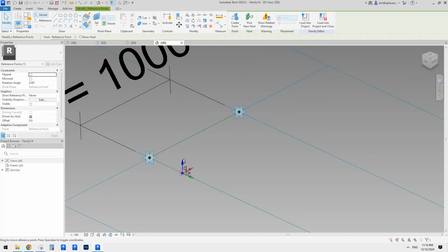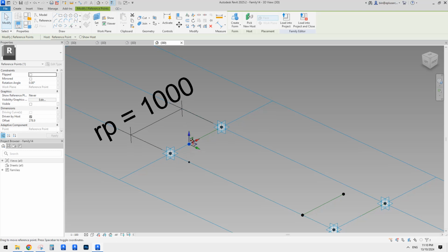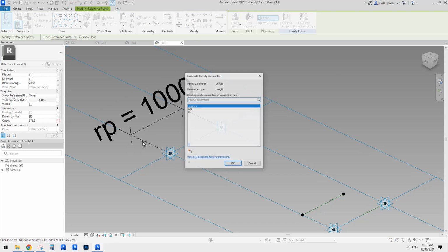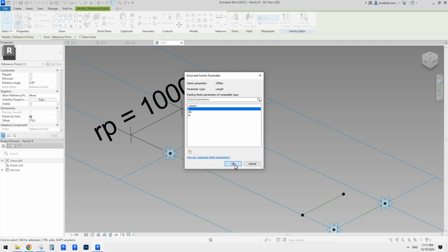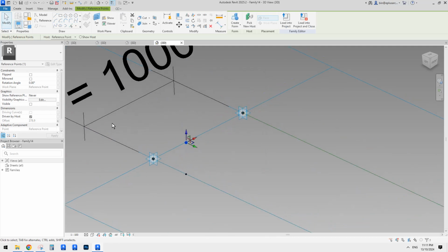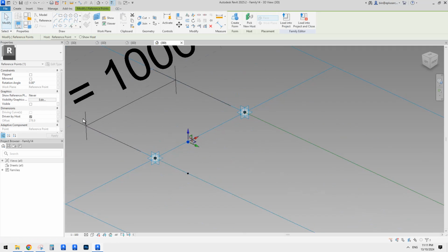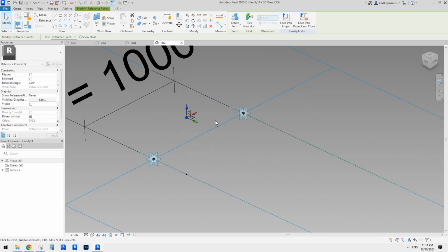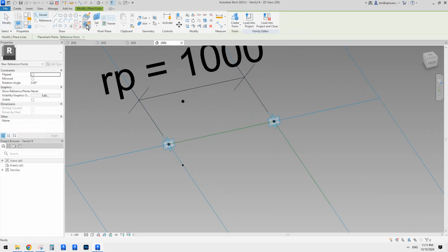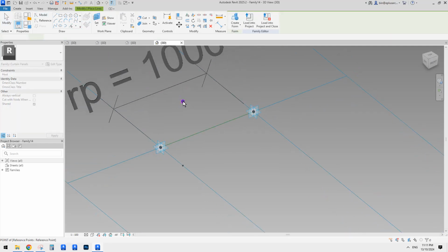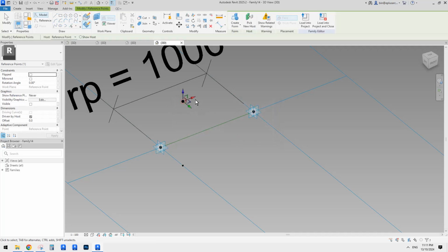So we need to give it a parameter. This will be the height of the panel on one side. I'll maybe create an H; just type is fine, unless you want to have different heights for different panels, and then you need instance. But if they're all the same, just use type. Now drag this up a little bit more. Then we place another point, set work plane, Tab, place onto the point, click OK, select the point, drag this way, apply that offset to it.